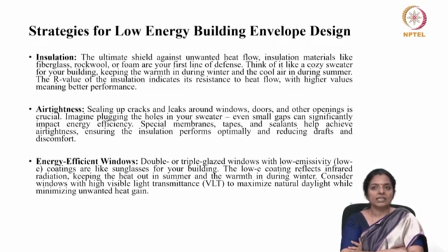Sealing up of cracks and leaks around windows, doors and other openings becomes critical. It is like plugging the holes in a sweater or in anything that is actually protecting you. There are special membranes, tapes and sealants which help achieve airtightness, ensure the insulation performs optimally, and reduce drafts and discomfort.